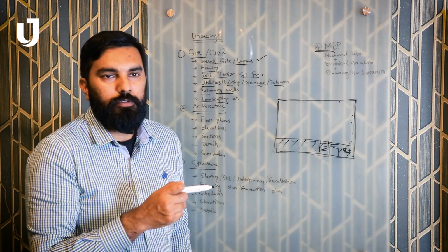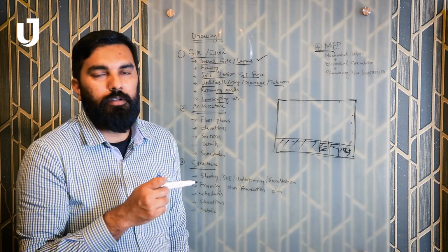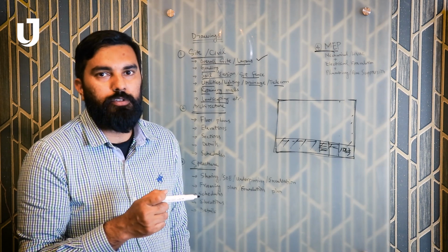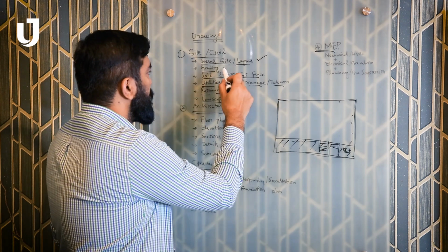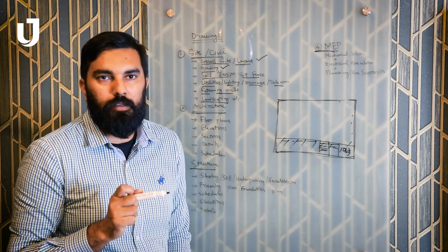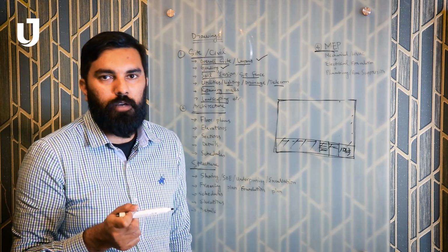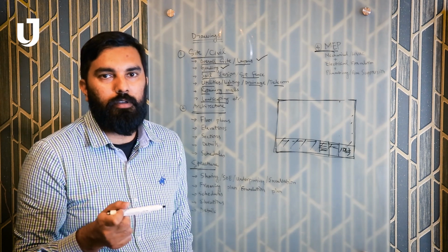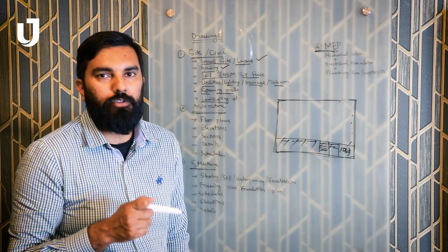And of course, we're going to be having the details, what's existing and what is going to be proposed over that particular site. Then we will be having a grading plan. In grading plan, we'll be having the contour levels, existing contour levels and new contour levels, from which we can easily have an idea about the cut and fill of the particular job site.